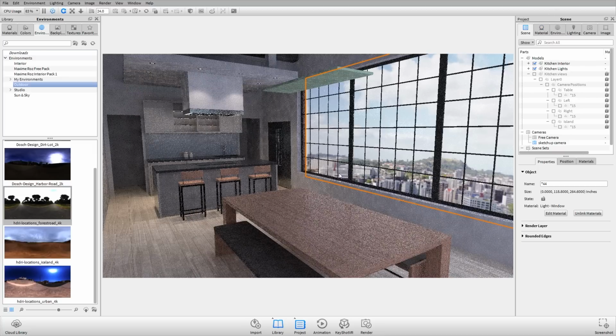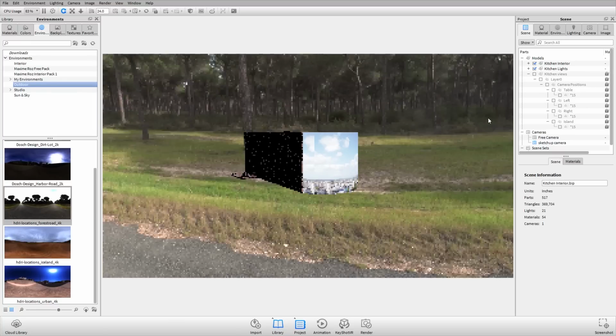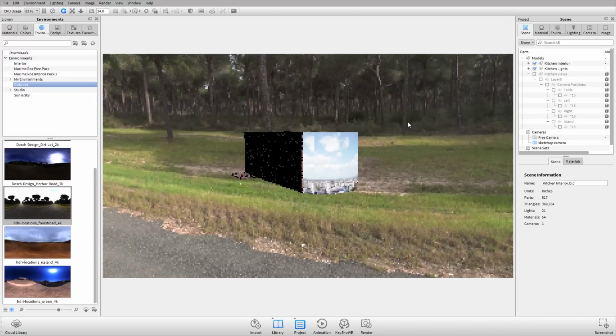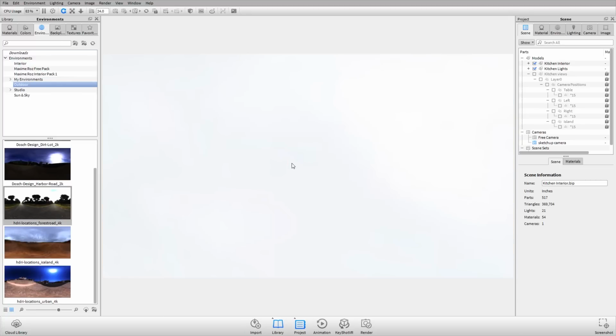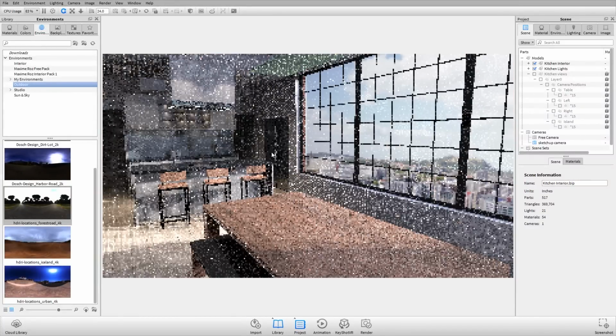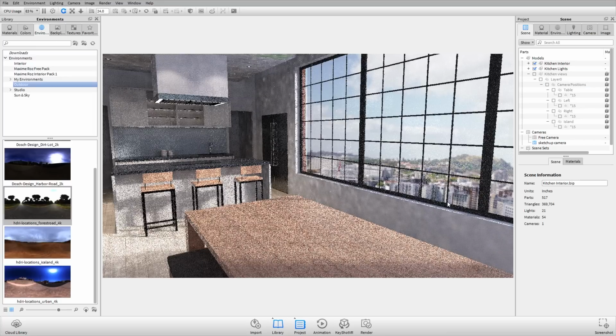It's a little bit tough to see right here, so let's throw this in performance mode. This is where my light's coming from. If I get it out of performance mode, you should see some cast shadows. Oh, I disabled my ground shadows. All right, but now our light from the environment's coming from the right-hand side. So let's zoom in and see what this looks like. Right, there we go. Now we have our environment actually casting that extra bright, sharp light. So this is now working with a combination of environment lighting and physical lighting.